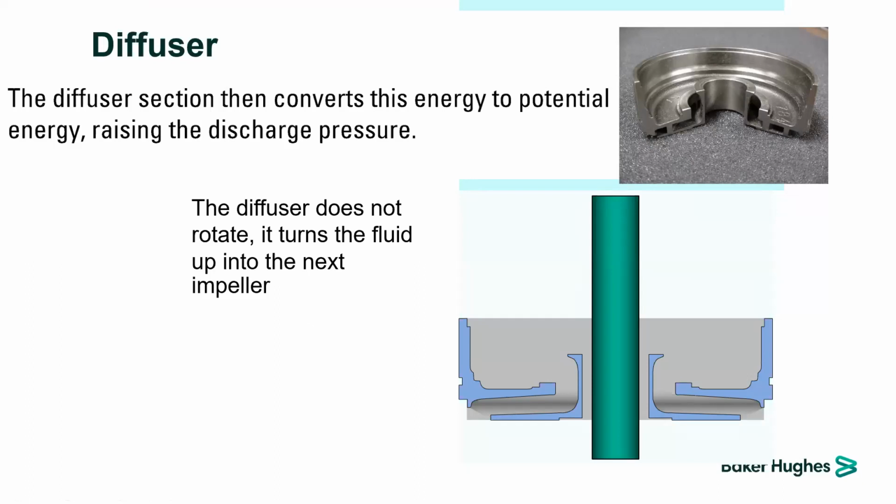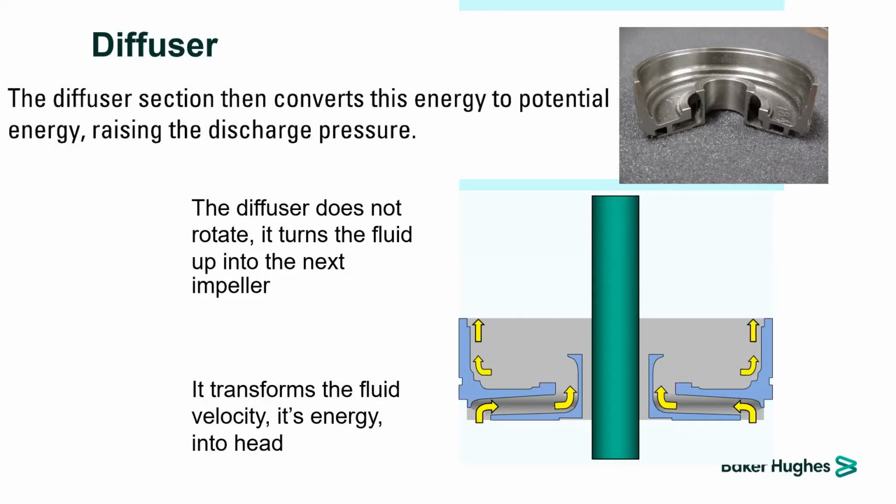You have to be aware that the impeller rotates with the shaft at the same RPM as the motor, while the diffuser does not. So please make sure you understand that the impeller is rotating with the shaft at the same RPM, while the diffuser is fixed. According to the illustration in the schematic, you can find the way of the flow. It goes from the bottom of the impeller through the eye and then to the diffuser.